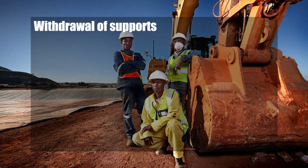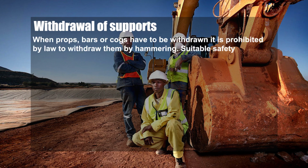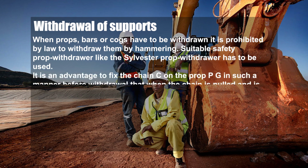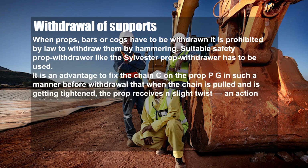Withdrawal of support. When props, bars or caulks have to be withdrawn, it is prohibited by law to withdraw them by hammering. Suitable safety prop withdrawers like the Sylvester prop withdrawer have to be used.